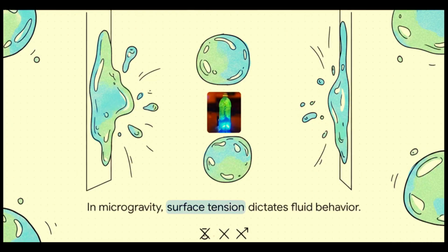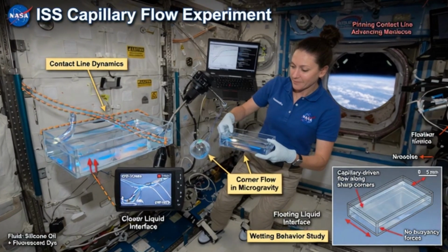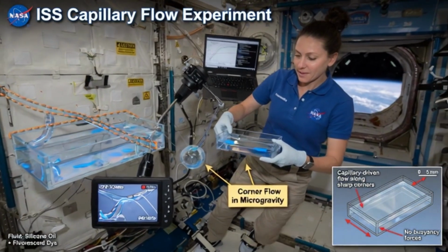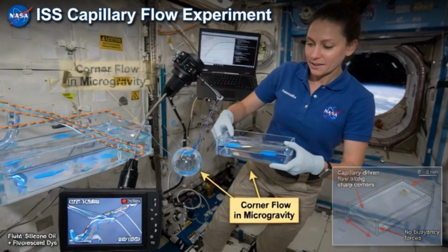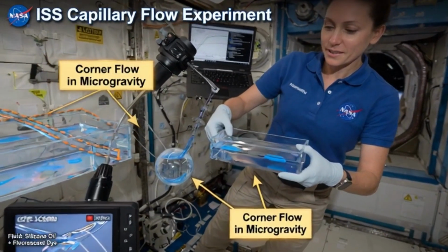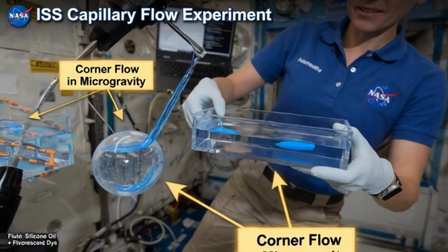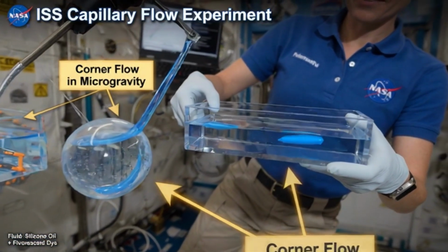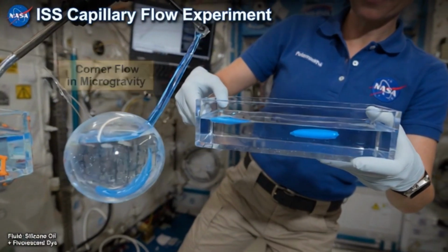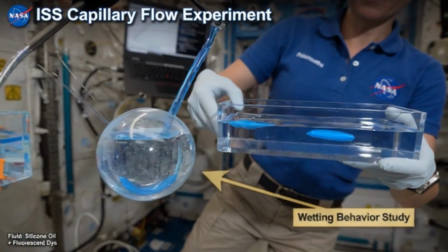But consider what happens to a fluid in a container when we completely remove gravity from the equation. In the microgravity environment of space, your capillary length essentially becomes infinite. The force of surface tension steps up and becomes the absolute sole dictator of how that liquid behaves. If the liquid is just free-floating, it forms a massive sphere. If it touches a wall, it will literally violently cling to it and spread all across the surface. Gravity just isn't there to pull it down anymore.